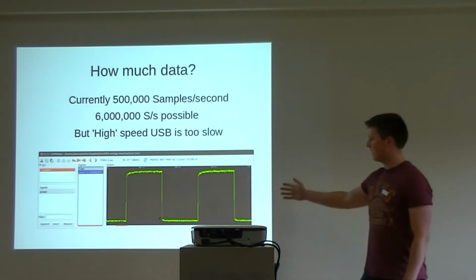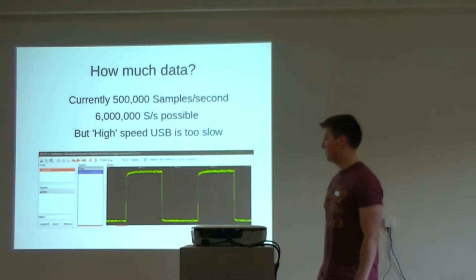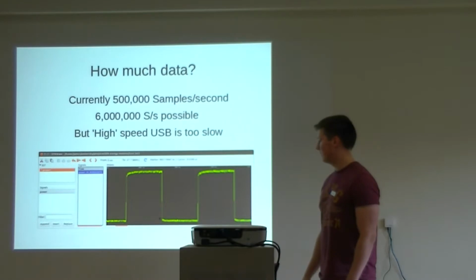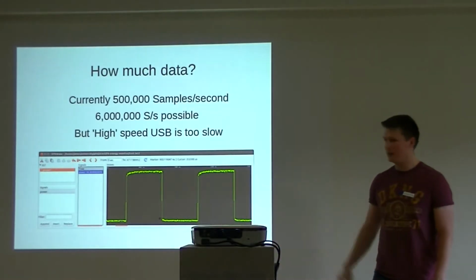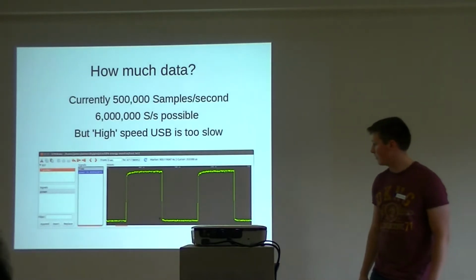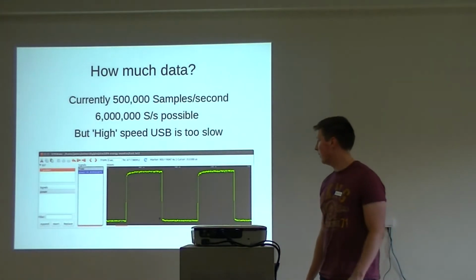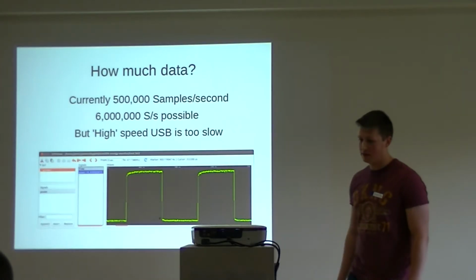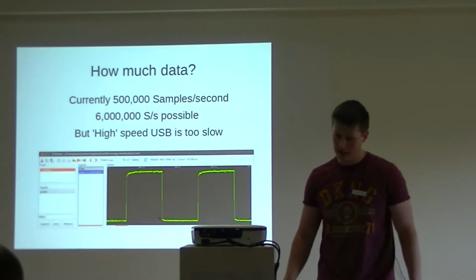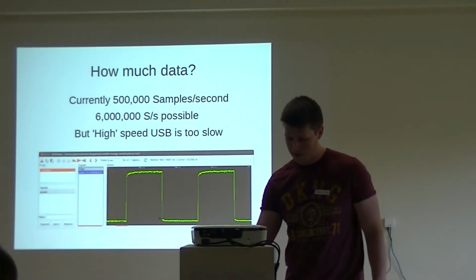So this was taken yesterday when I was playing with an Arduino. It's on when it's flashing an LED and it's off when the LED is off. So this was flashing fairly slowly, but you can see the power draw goes up significantly when you've got the LED turned on. And that's because the LED takes about 30 milliamps.